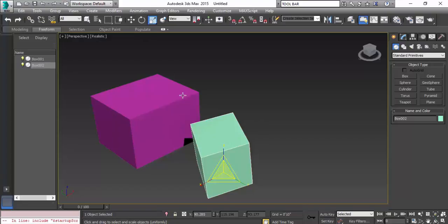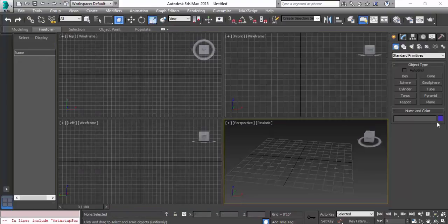When you click on W, you can see here, this is the select and move, it gets highlighted. R, scale. We have three types of scale: scale uniform, non-uniform and scale and squash. And if we click E, this select and rotate will get highlighted. So you can click the shortcuts WER, or you can get it from this main toolbar.